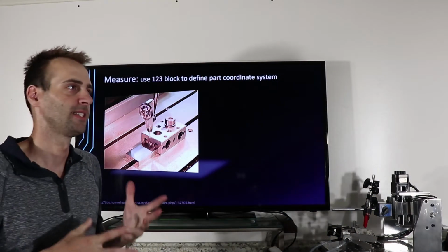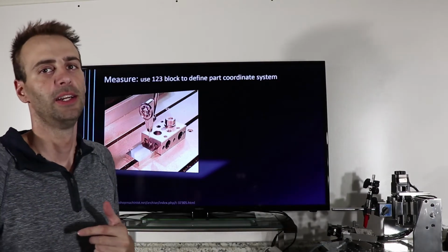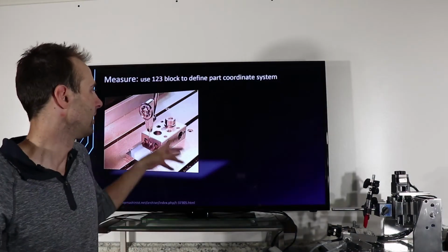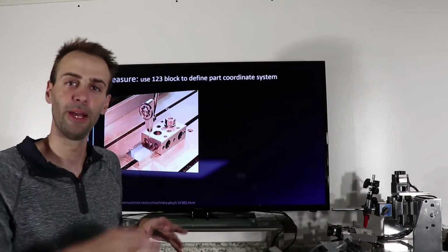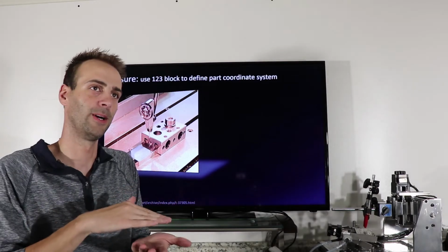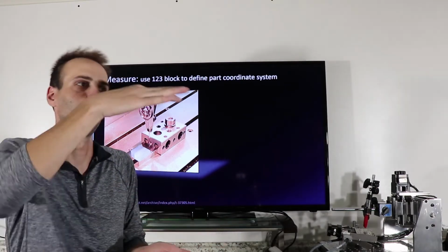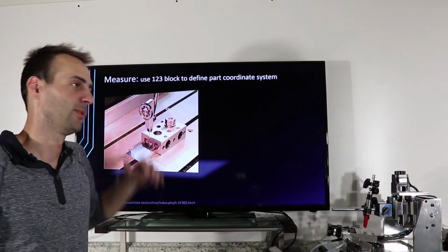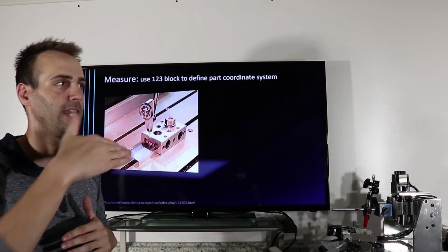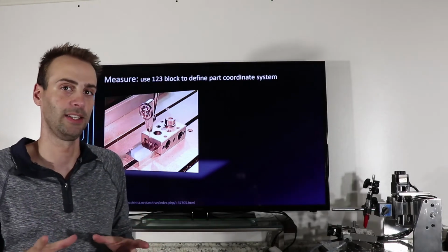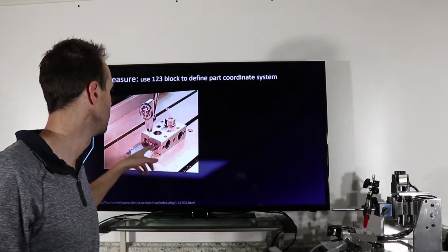So again, as this is for the DIY community, let's assume that you can get your hands on a 1, 2, 3 block or something like that. And if it's just a flat bed, bolt it to the table. Or if you normally bolt your fixture down and then your part sits on top of the fixture, raise that block up, okay? Get it to where your parts are normally made. That eliminates roll errors and things like that, okay? That's called the Abbe offset, A-B-B-E offset, okay?